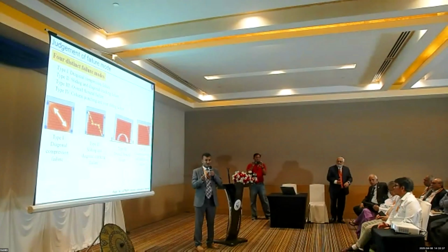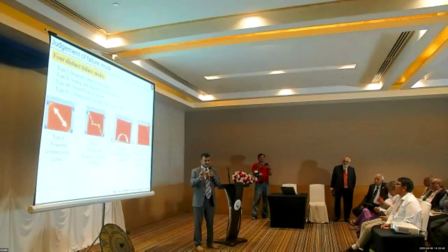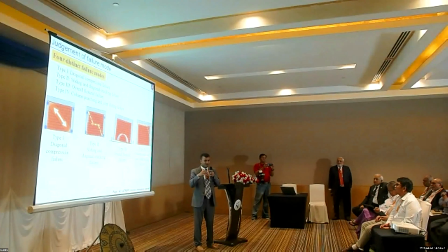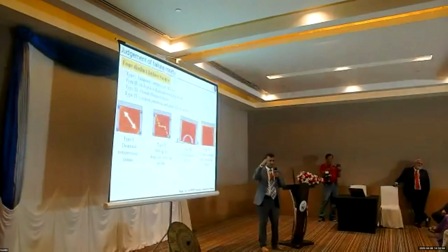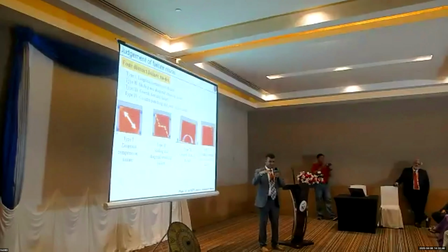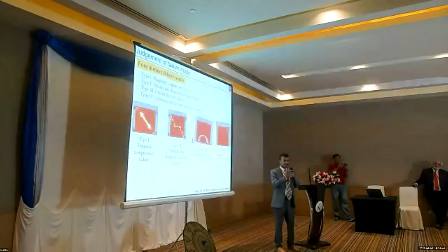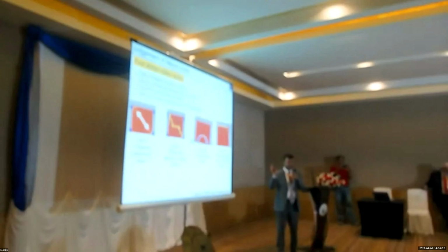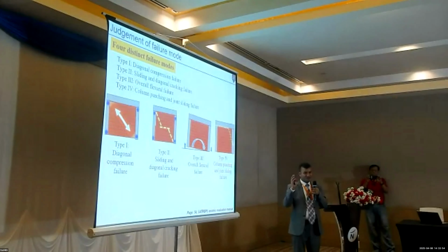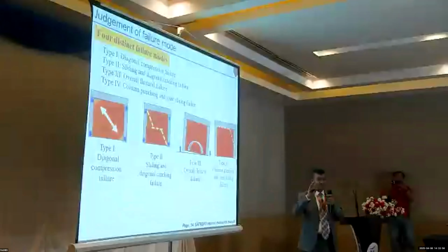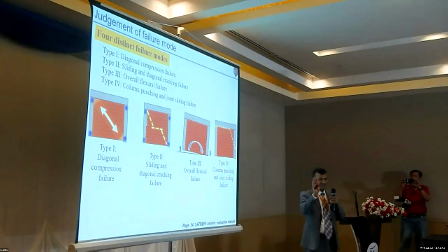Yes. Actually, I just want to add, during the design stage we don't consider masonry for lateral force. For a mid to high-rise building, we need to calculate the lateral force, and we just consider columns and also RC walls or something like that. But masonry walls, we don't consider. But after earthquakes, we found that this masonry infill changed the behavior.